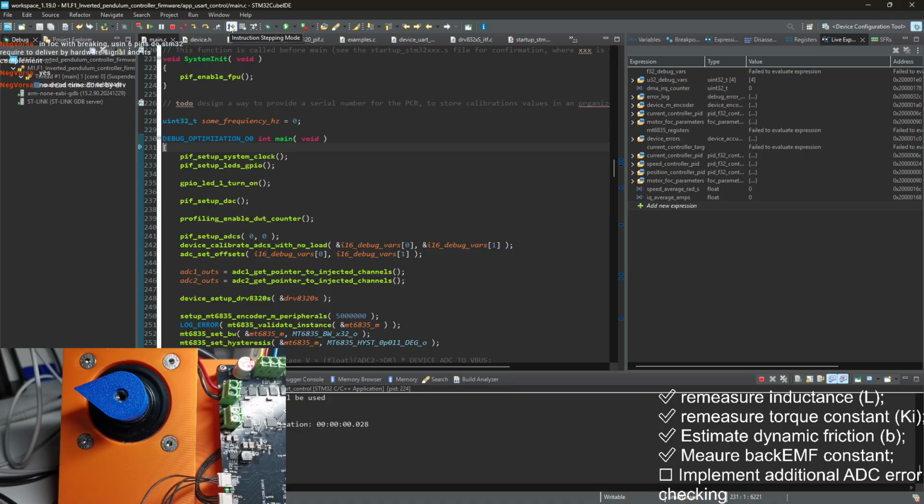And if you use brake resistor, it can be a separate channel. But it has safety of dead times, right? Yes, it does. So it can provide dead times itself, hardware-wise, and they are very good because they measure voltages. They are not time related, they are voltage related. So the drivers measure gate voltages and apply the dead times based on that, which is very nice because it guarantees that you don't waste any time on dead times you don't need. So the driver is very good from this standpoint.